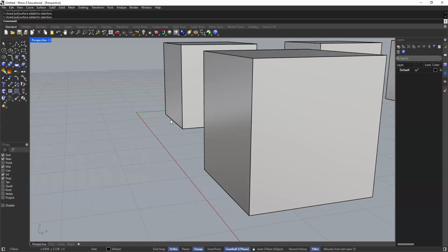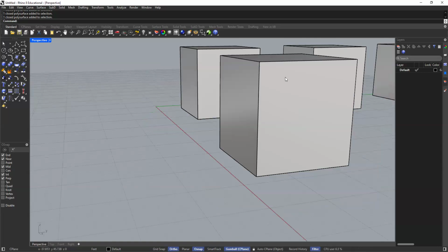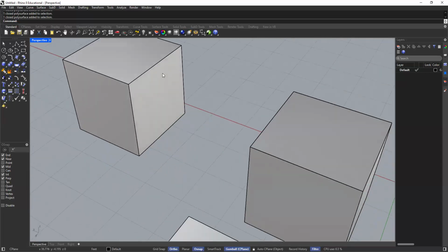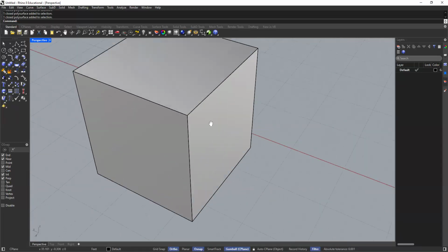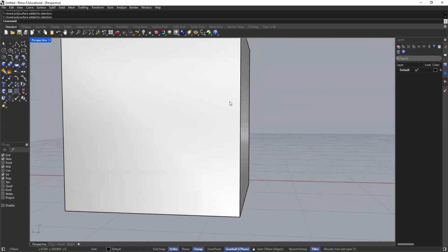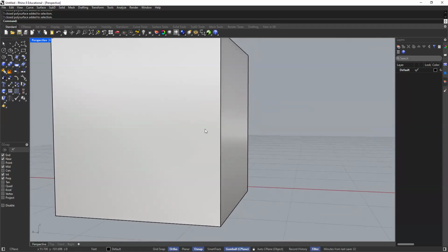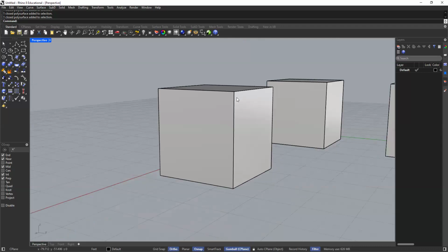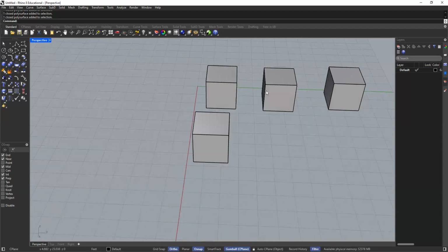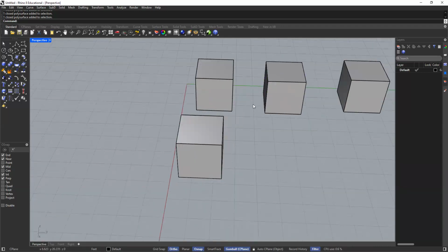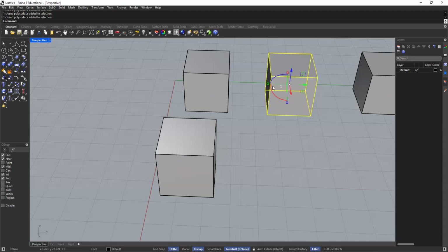surfaces, because you're also going to have the wall surfaces on top of one another with the cabinet surface, and you'll have the floor surface overlapping the floor of the cabinet. So you're going to have to select every single surface, and that's going to be a nightmare, right? That's really going to test your ability to kind of get inside the walls, all sorts of things. So you really want to try to avoid exploding a polysurface, unless you have to. Or unless it's extremely intentional.